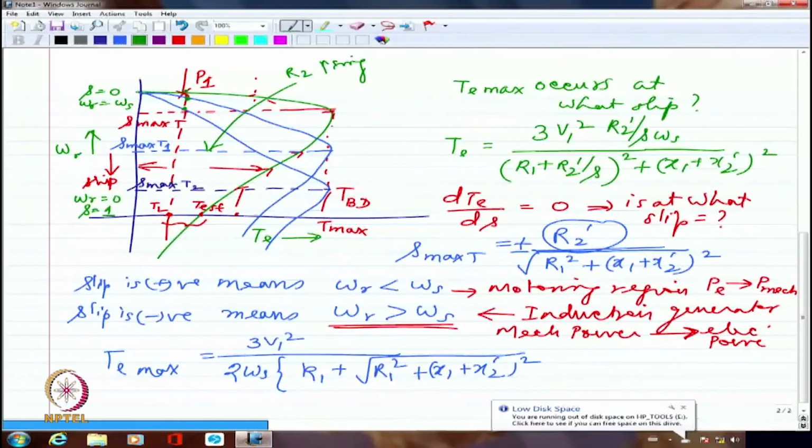So the rotor resistance control for controlling the speed of an induction motor at a given torque is possible only in the case of a slip ring induction motor, which is a big plus point because, although I am incurring losses, I am able to get a very simple method of speed control. If I want to have speed control, no matter what, I don't mind losing out on efficiency. In that case, one of the best means possible is to include rotor resistance, because it's very simple. Just include a rheostat, keep changing it. That's it. It's not a big deal.